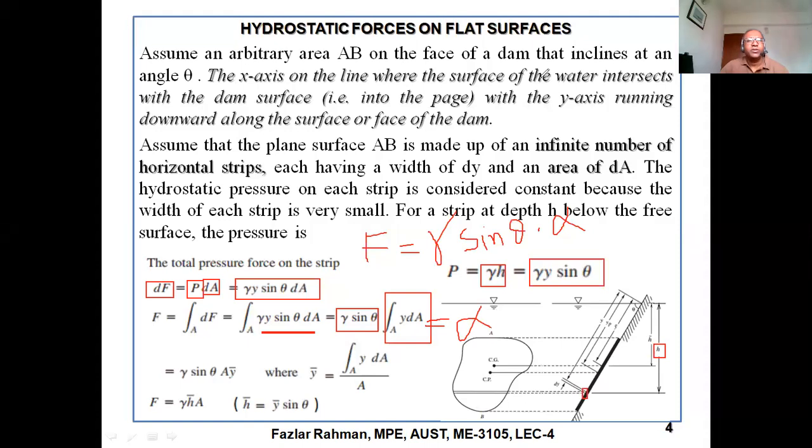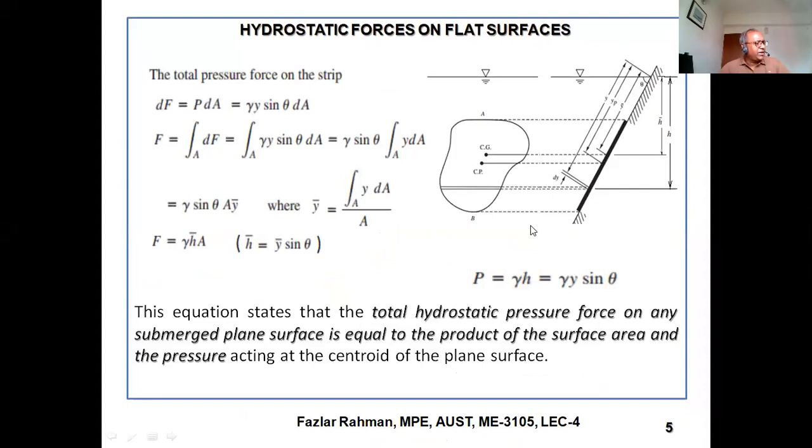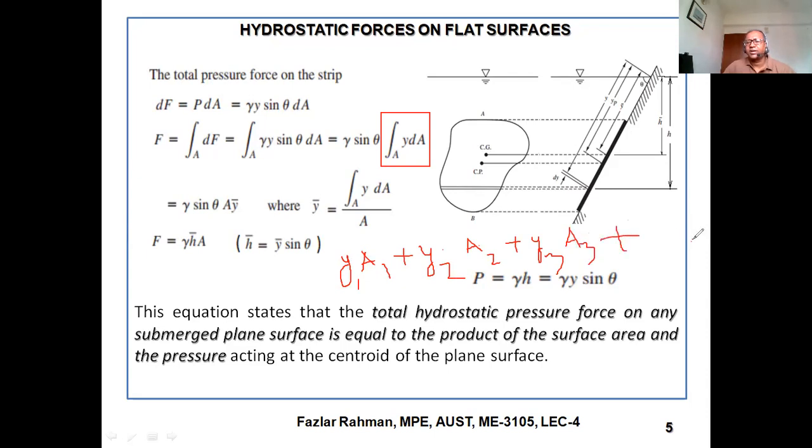Now, we need to understand the integration portion. What is the meaning of y dA? This portion, you see, is an integration on area. So I can express it with this term: y1 into area A1, plus y2 into area A2, plus y3 into area A3. Integration means summation.